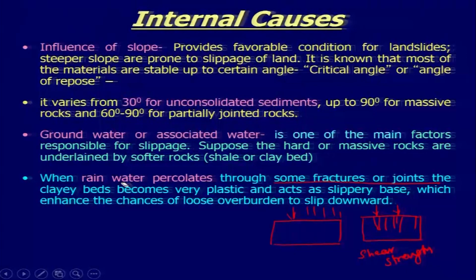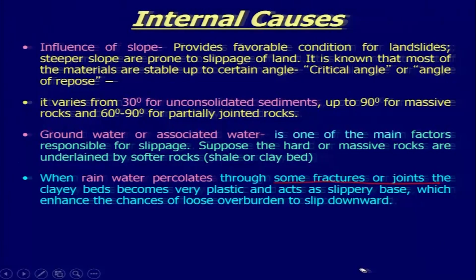So, when the rainwater percolates through some fractures or joints, the clay bed, or even the rocky succession, will lose the shear strength, but in case of the clay, it will become plastic and act as a slippery base. Even if you are having hard rock sitting on the top, if you see just the surface, you will feel that you are safe, nothing will happen. But if you are having the clay bed as well, I'll just put it very quickly.